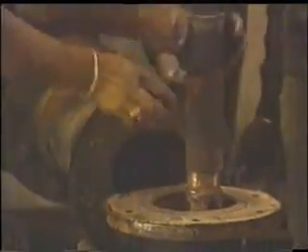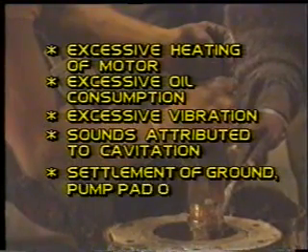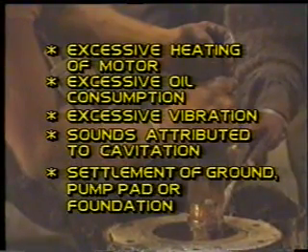During routine servicing and lubrication of pumping equipment, care should be taken to observe and record excessive heating of motor, excessive oil consumption, excessive vibration, sounds possibly attributed to cavitation, settlement or cracking of ground, pump pad or foundation.